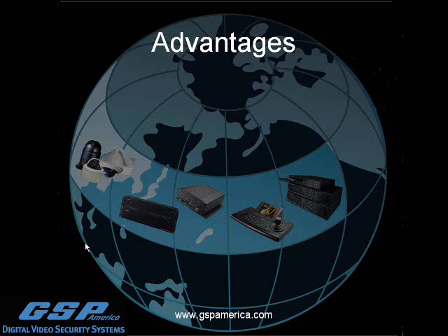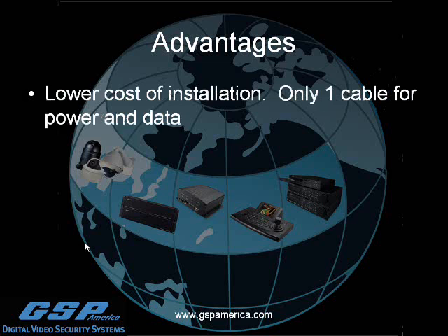So real quickly here in closing, I just want to mention some of the advantages of POE and why people are using it. One big reason is lower cost of installation. You've got one cable for power and data, so you're not running separate cables for power and separate cables for the data.